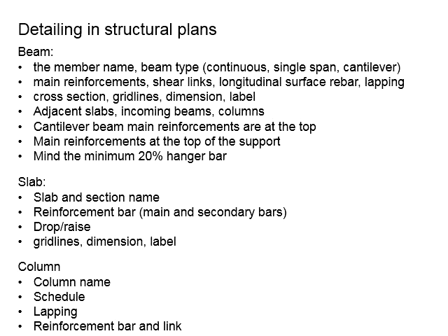The grid lines and dimensions may be clear in the technical drawing, however, in actual situations on site, those are imaginary. Therefore, it would be good to clearly indicate the incoming beams as per their exact size, so that it is easier for the contractors to identify which slab is which on site.